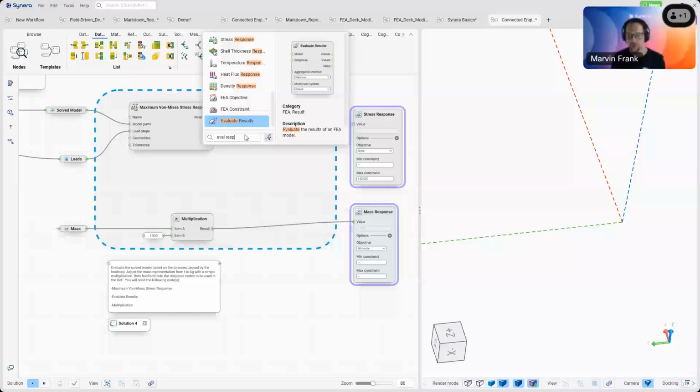But in case they are there, we could split these disjoint meshes. What I do here is calculate the area of all the meshes, and of course, our main mesh has the largest area, the largest volume. So we sort by the volume, then filter out everything and only keep the largest volume or largest area mesh. We do a quick smoothing. So you see that is slightly smoothed. We only do that because it might be easier for the next step.